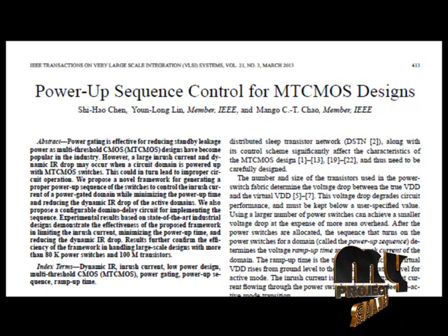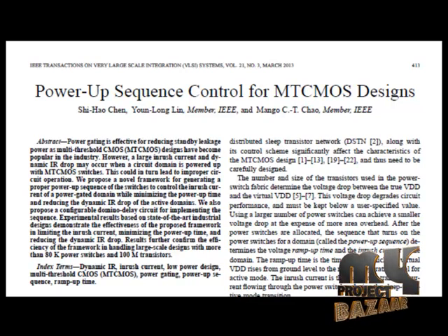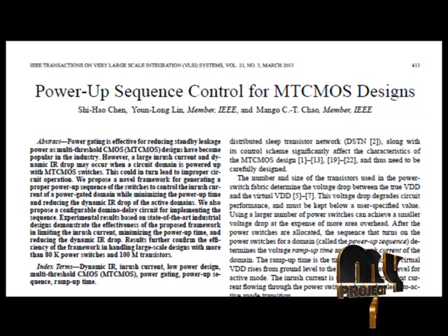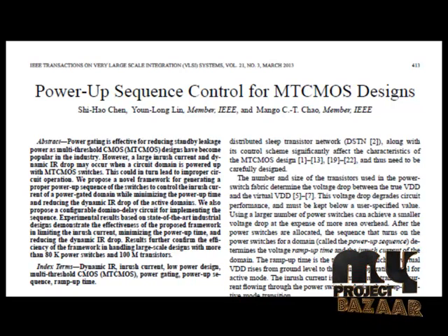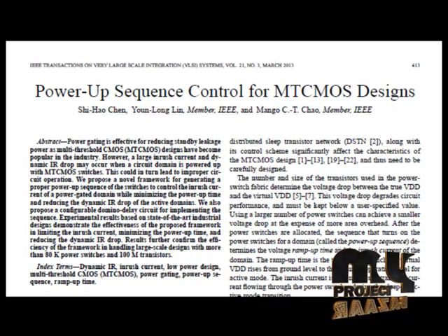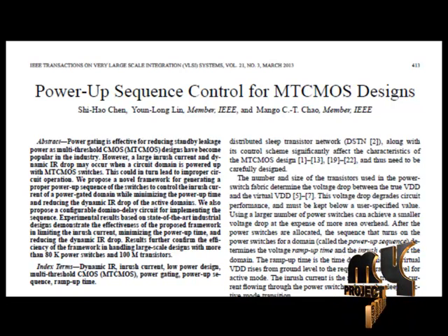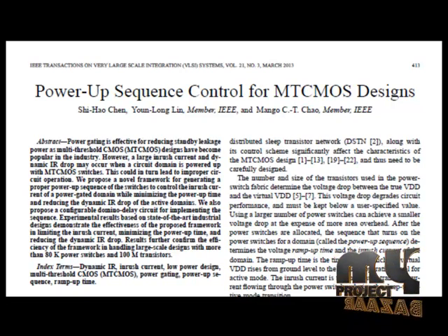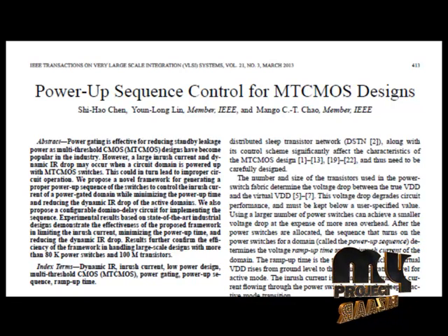Many asynchronous circuit families are robust to a wide range of supply voltages, ambient temperature and power variations. We exploit this robustness in the context of power gating to enable a zero delay wake-up scheme for pipelined computation. The first token traveling through a pipeline turns on downstream pipelines, hiding the latency cost of wake-up in the computation time of upstream pipeline stages.